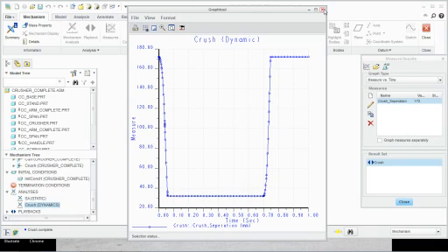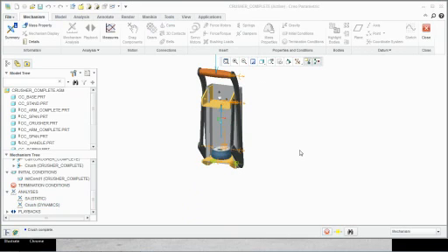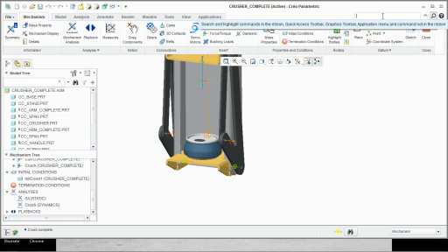All right. Now all this is good. Like, what am I going to get out of it? Right? Now I need to know, hey, what kind of forces act on this particular part. So I want to send this analysis results into Mechanica. So there is an icon which says use in structure.